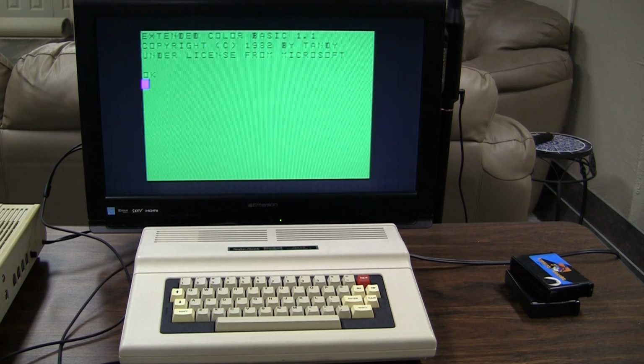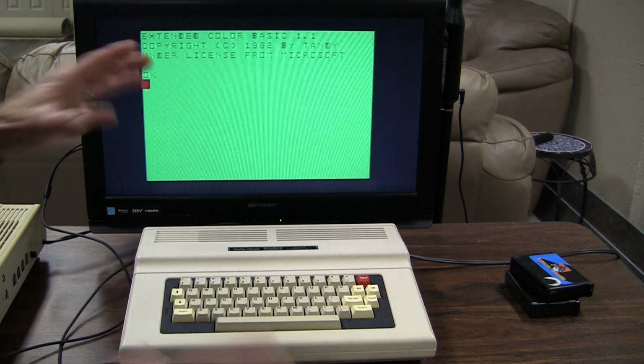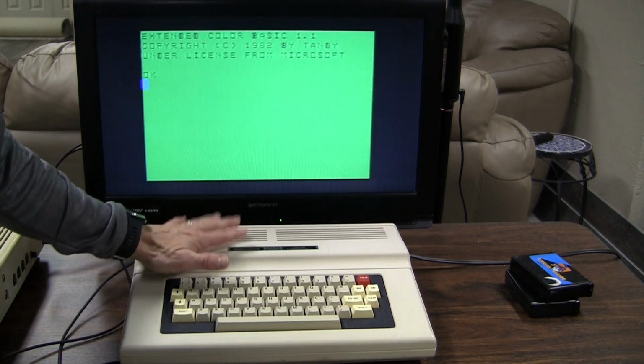Not too bad. Again, a little room for improvement on the composite mode. And in the future, I'll probably do another look at the other circuit for composite video that we saw in the CoCo 1 schematic. But this is pretty good. It's probably as good as the old RF modulator, and at least it doesn't have that static interference in it that came from touching the case.